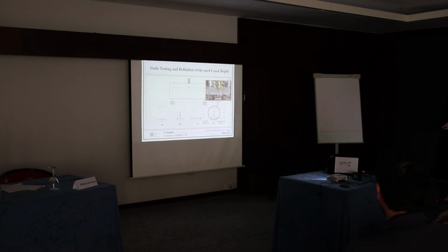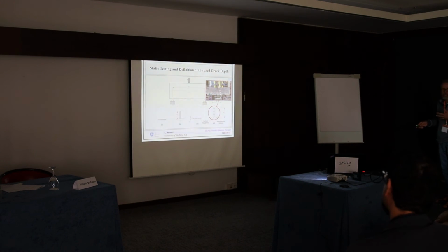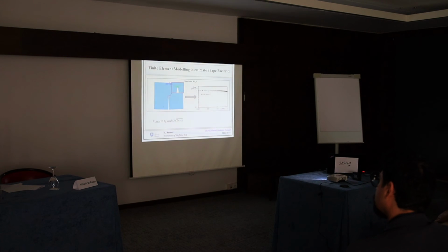And also when we had this series of defects, we defined an equivalent crack length, assuming that there was no cohesion between adjacent sausages of material below a certain level, and it was very easy to observe the level where you had this manufacturing issue, because intentionally we were creating those bad specimens. And this is the final result.